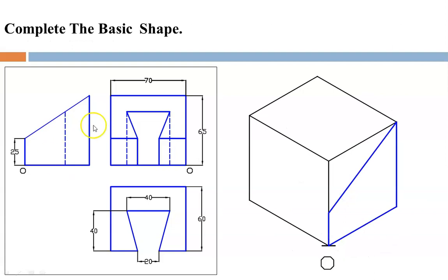If you go through these 3 views, the side view is very easy to draw and it gives you a base shape of an object. Considering this base shape, the outline here you can see, so this is a 60, so darken this, so here it is, you can say 60 complete line is darkened, then 65 is also darkened, completely. Now from origin 25 mm up, so here you can see the line 25 mm up, and now from this point you have to draw a line in such a way that it will connect this highest point. So this shape is now completed on the RHSV plane.